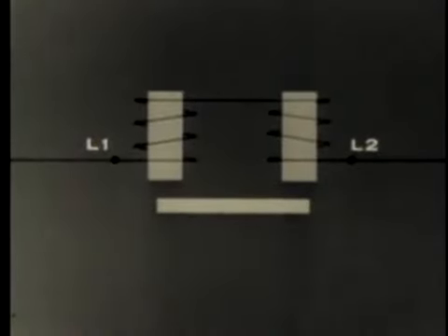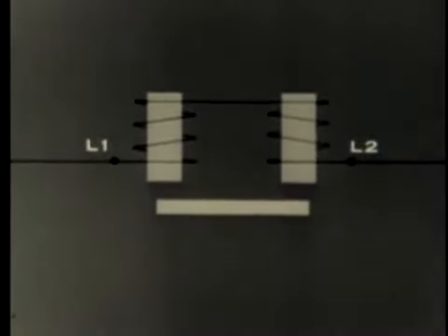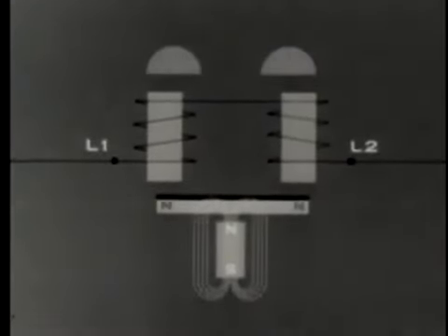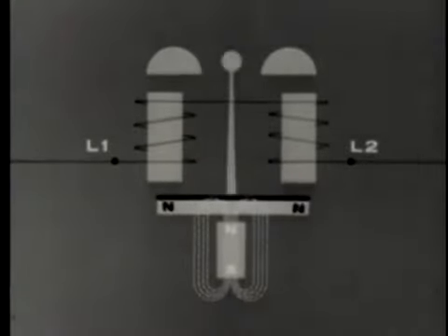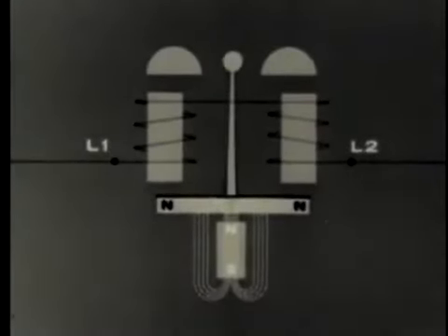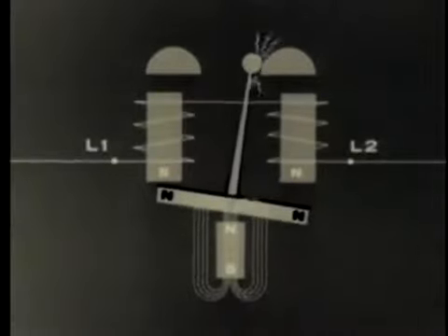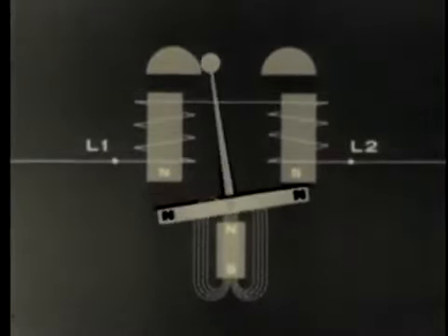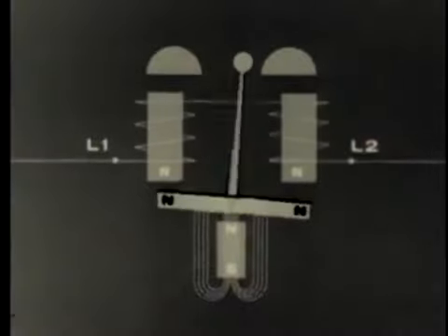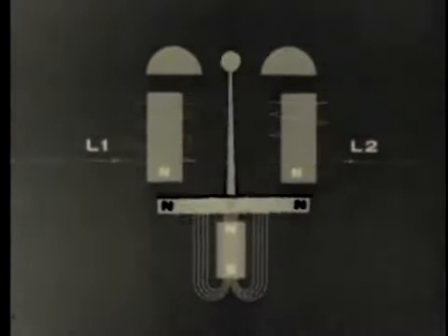If we introduce a soft iron armature near the base of an electromagnet, and then introduce a permanent magnet to polarize the ends of the armature, an unstable condition will exist when current flows. When a signal is sent over our line, the polarity of our electromagnet will alternately attract and repel the ends of the armature operating the clapper rod, which alternately strikes each gong. Here we see an actual telephone ringer in operation.